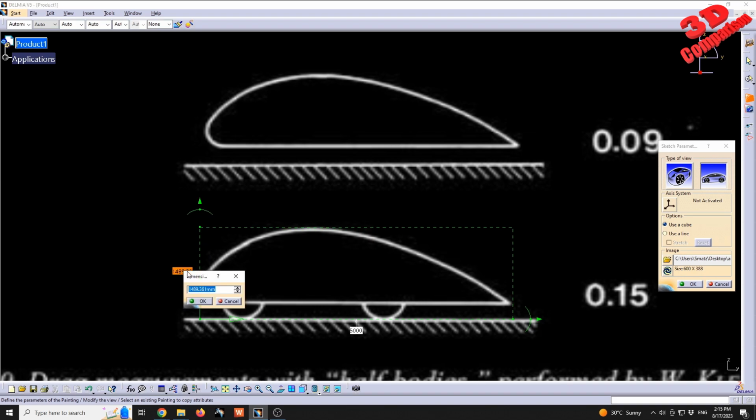I will just go with this. We see that since I swapped that, the two dimensions are linked. So that means that if I adjust one of those by inputting a value, the other one will also be influenced. So keep that in mind when you are, let's say, positioning this.